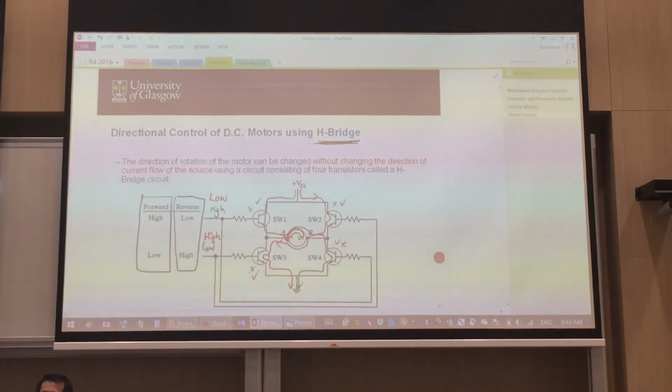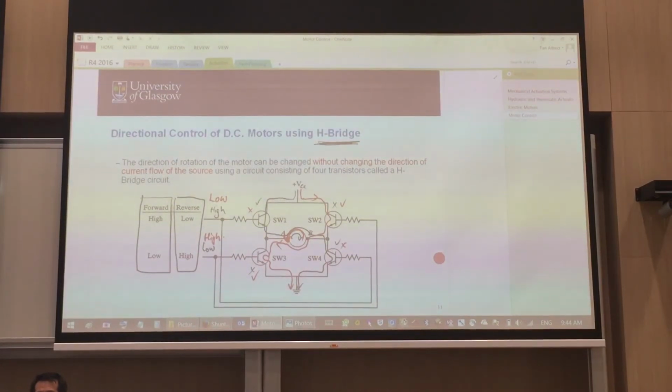So that's how we make use of the H-bridge and PWM signal to rotate your motor in a clockwise or anti-clockwise direction. These are some techniques that you can use for your FYP or even for your Lego robotics lab, if you want to adjust the speed of how fast your robot will move through your motor, which is your DC motor.